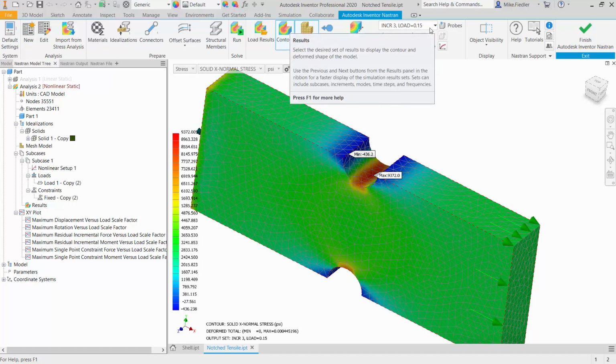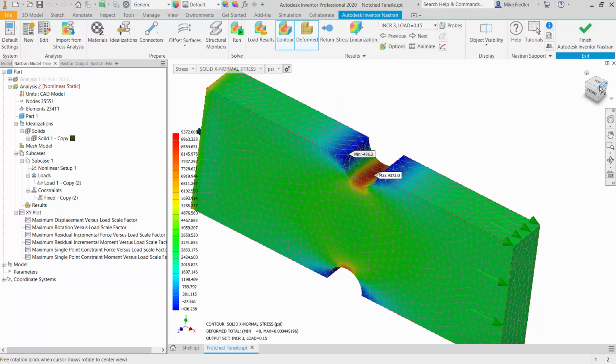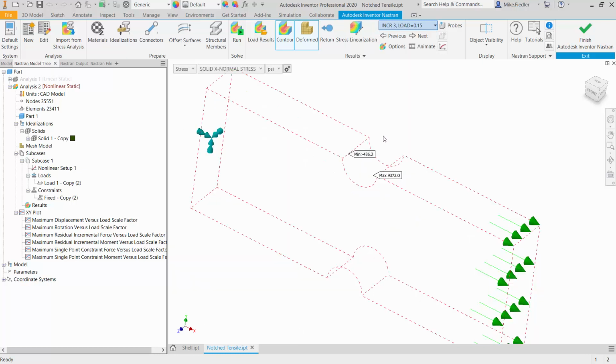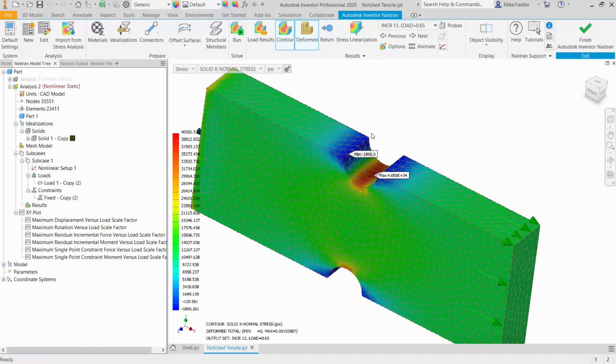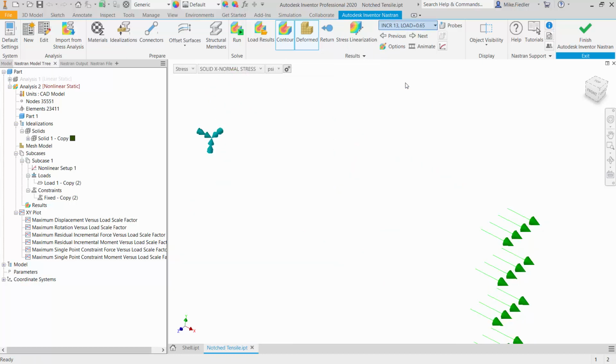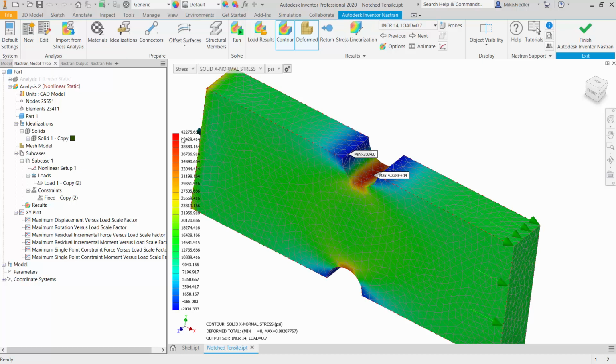9,000, so it's going to keep adding 3,000 to it, because again it's a linear modulus of elasticity, and we said 20 steps, so it's breaking up that 20,000 psi into 1,000 psi increments, so I can see nice linear results. And then my stresses should just increase by 3,000 each time until we get up into the region where the material yields. Right, there's 40,582 at step number 13, and if we go to our next step, we go to 42,275.